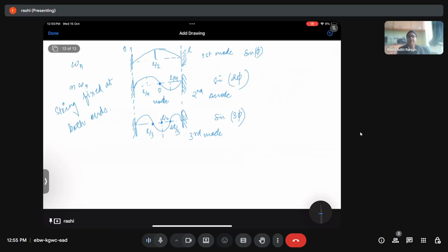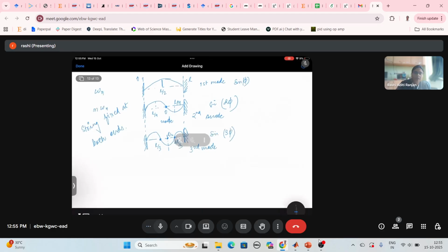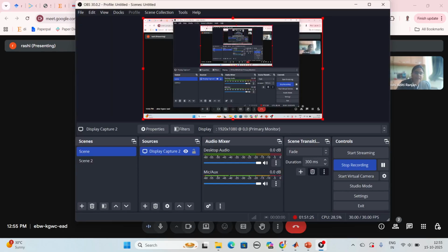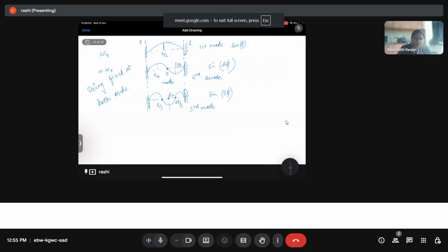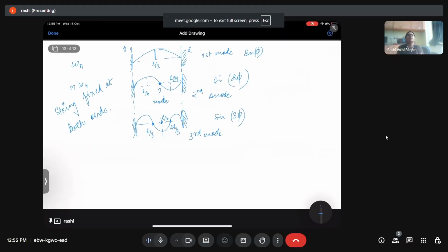so I hope that this is clear, how we are going to model a continuous system. Anyways, these were some cases for the bar, the beam, and the string, which we considered because it was easier for us to get the solution for the partial differential equation of these. Anyways, it seems easier, it is not that easy. But when you talk about a practical system, we don't usually rely on getting the analytical solution because it's a complex system. So we prefer FEM analysis, finite element modeling.